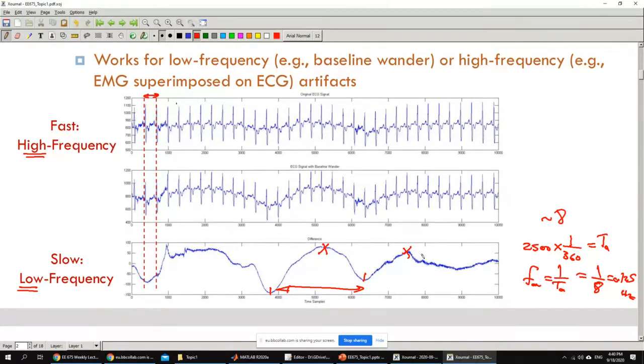What you need to do from something like this is just get to a point that is close to what you want. This is not exact. You just want a rough, engineering estimate to start with, and then you optimize through experiments. You get that value, design a filter, and then try another one, a little bit smaller, a little bit larger, so that you get to the optimal value by experimentation. But here, you just want a starting point for filter design.